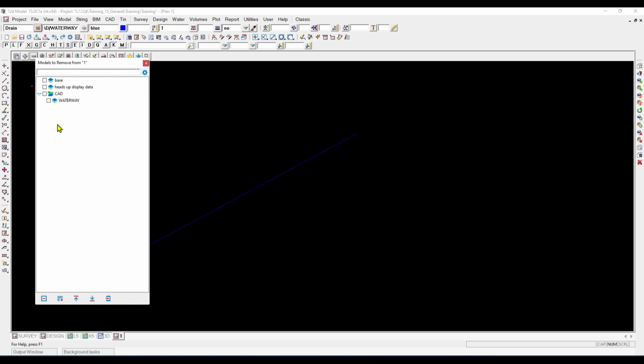For example, if you're a surveyor and you've gone and done a topo and you've named your function topo day one, you can simply give all your models a prefix of topo day one slash, and all your models from your topo will go into topo day one. And so you won't have screeds of models here. You will simply have a folder called Topo Day 1, and you can open that up and go and find the models that you're after.